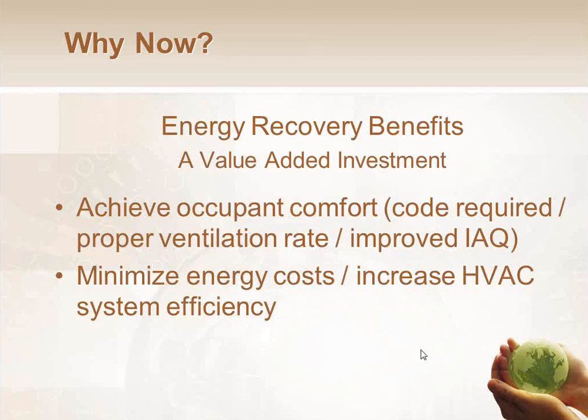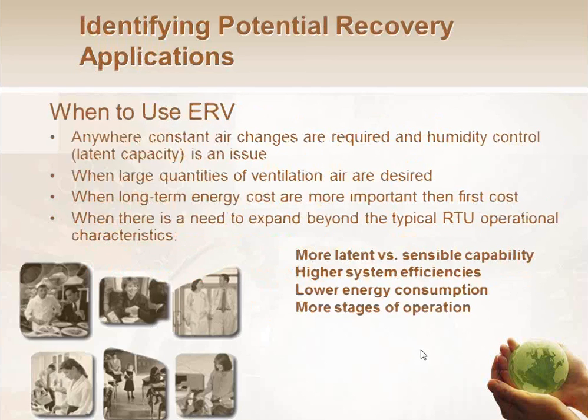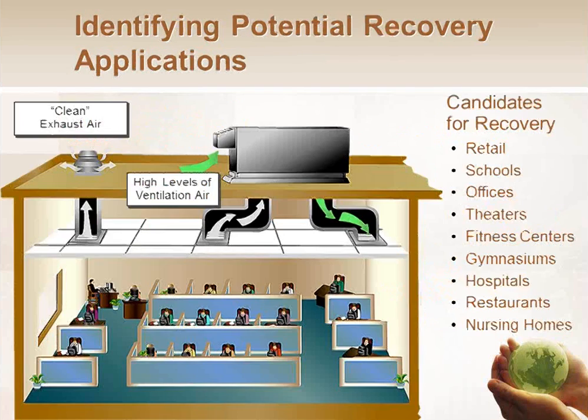All right, so what types of buildings do we want to put this in? I just said data centers probably aren't a great candidate. Not that you couldn't do it, it's just not the best candidate. The best candidates are the ones that have very high ventilation rates, which are ones that have typically lots of people. So schools are great, auditoriums, movie theaters, offices, nursing homes, sometimes restaurants, depending on whether somebody chose to steal the dining room air to make up the kitchen hood. If they chose to do that, then it's not going to be a good candidate because you're not going to run grease through an ERV.